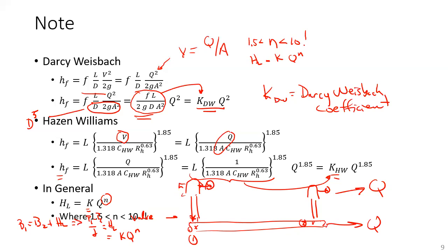And that's what people sometimes don't understand. If you go out there and just put the pressure gauges on the hydrants, you may have 70 PSI, plenty of pressure. But once you open the valve, or once you have water flowing in the pipe below, the pressure just drops precipitously. So for example, in your house, you have 70 PSI coming in at the curb stop. And once you turn on the faucet, it just dribbles. And that's because between the faucet and the curb stop, you've lost all of the total energy through friction losses.